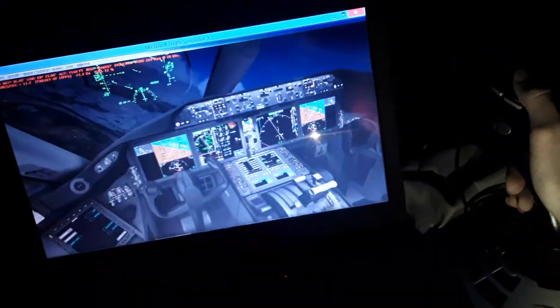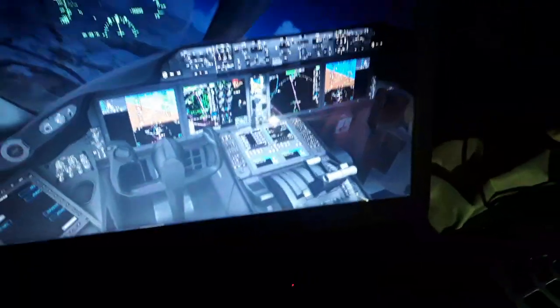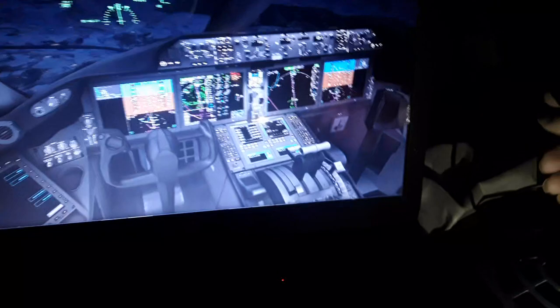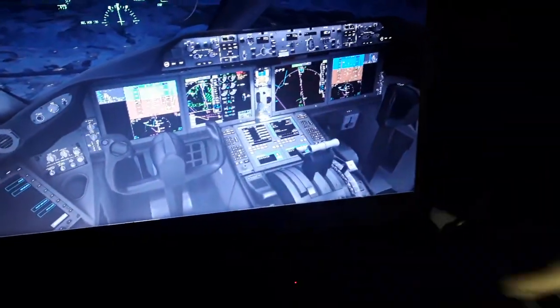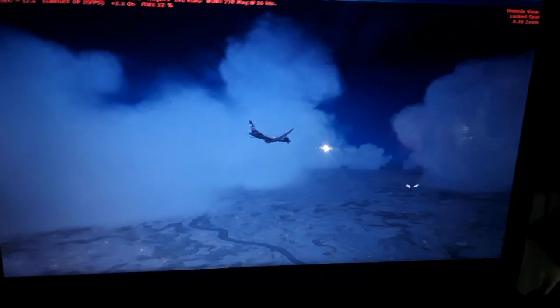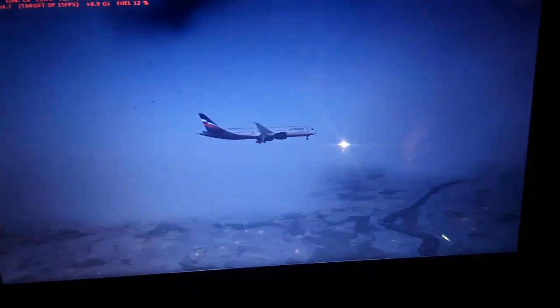We are in a very good position, so extend a few more flaps, and we need a little bit more airspeed, and landing gear maybe down. So we are here, you can see, approaching, full landing.